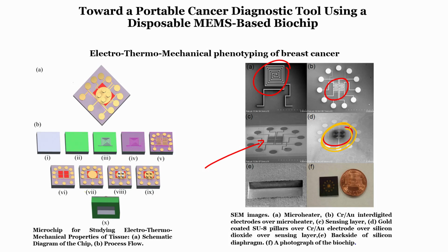So, if I follow this schematic, what we have seen? We have taken a silicon wafer, this is oxidized silicon substrate, this is a nichrome, we have an insulator, we open the contact of the insulator and fabricate interdigital electrodes. Over that we have piezoresistive material, then we have insulator, we open the contacts like this, 8 of those, and then we deposit a gold and pattern it. So, we are on step number 7 right now.